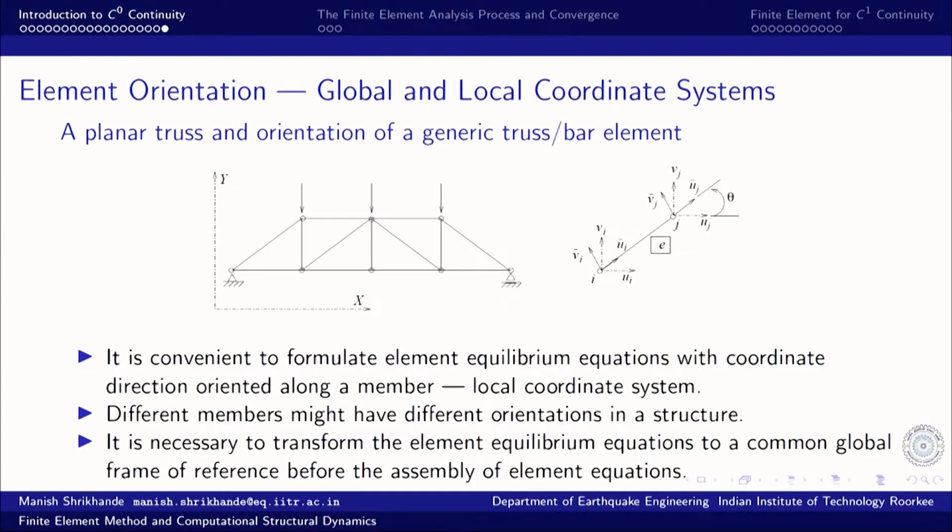So, this in effect completes our discussion of finite elements of C0 continuity. In structural mechanics, it can be used to model truss or rod kind of problems, or even torsion of a circular shaft, because the governing differential equation is a second order differential equation, and the highest order of derivative in the weak form of the weighted residual statement is the first order.